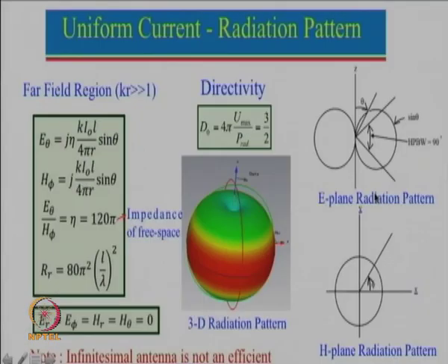Now, for this dipole antenna, let us say we are standing here, we see the full length. As we move along, and if we see from the top, all we really see is the tip of the pen. So, we will see very little, and as we move along, we will start seeing a little more. In fact, the dipole radiation pattern is very similar to the way we look at this pen. The dipole pattern will be maximum along here, then it will go from maxima to 0, then again it will go to 0, and go to maxima. So, one can now see the pattern.